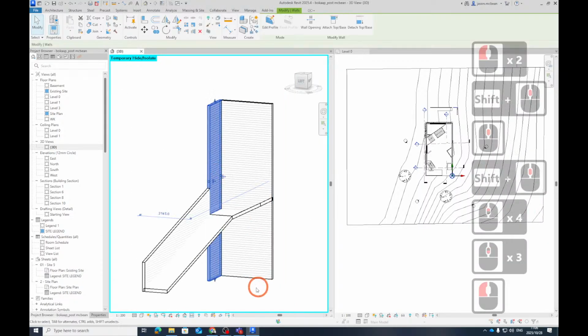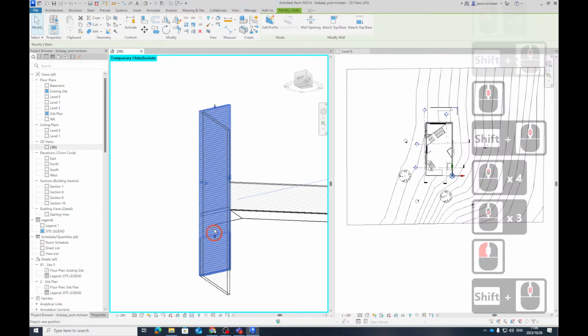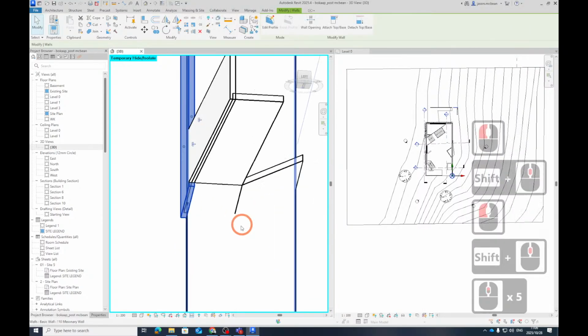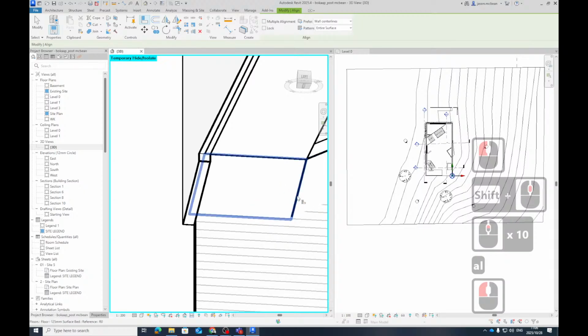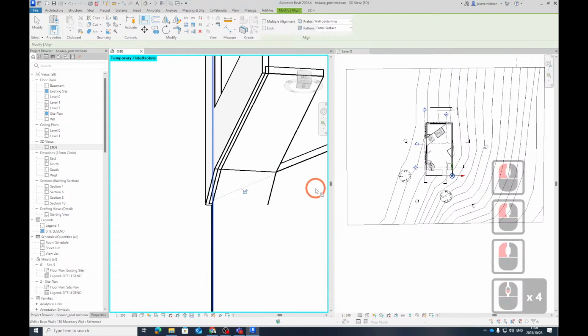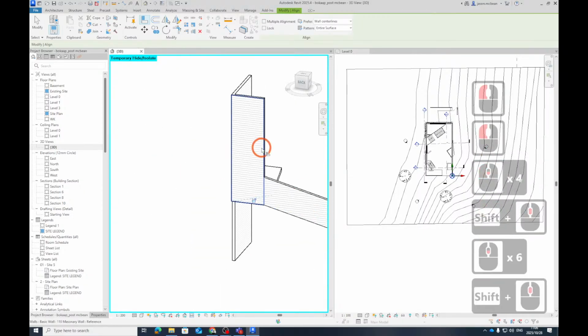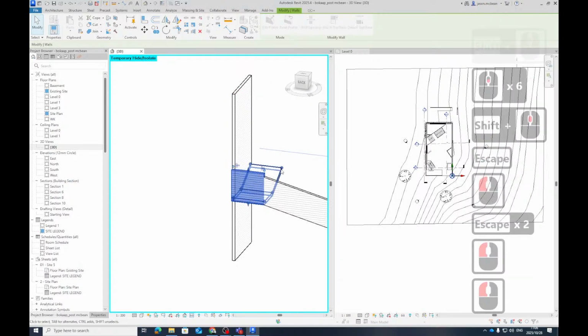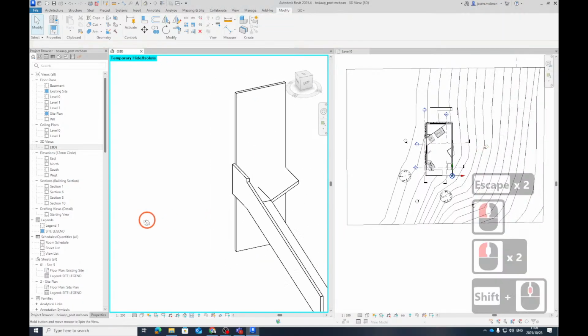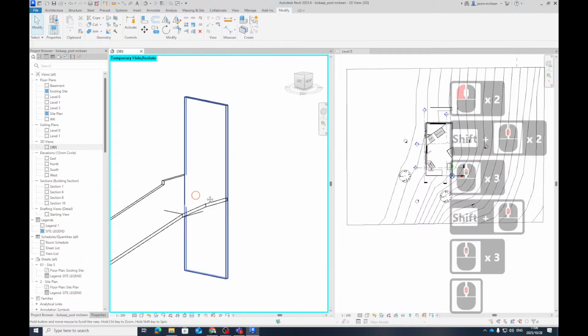So you can go and customize this. Look, if it's flat, you don't have to, because watch how quick I can do this in 3D. Align command, so I'm using align command. So the underside of this, that, bang, done. This one, I can maybe make its height where it stops. Because it's not changing, but this one, because the profile changes, I might have to use that other approach.